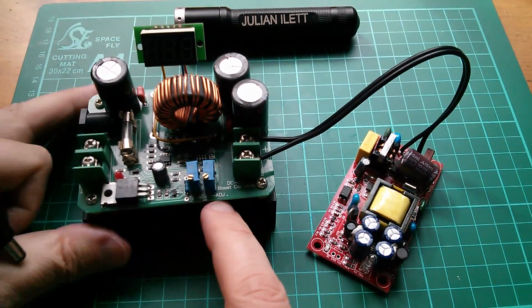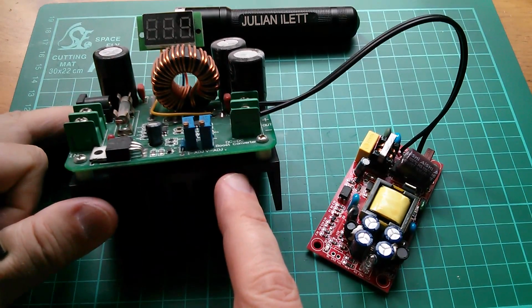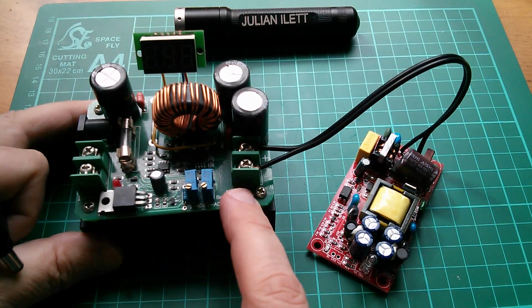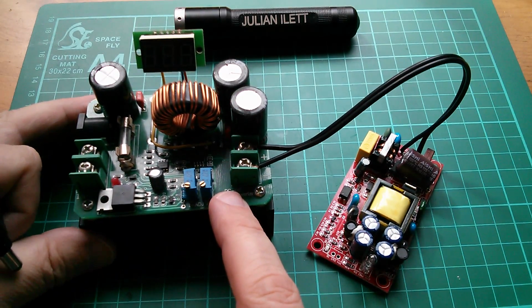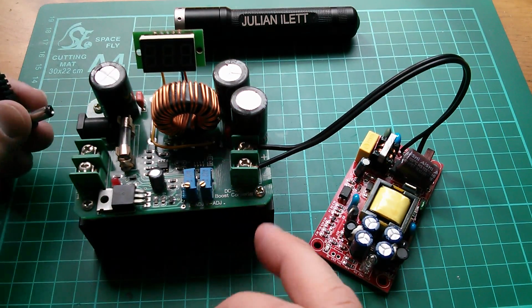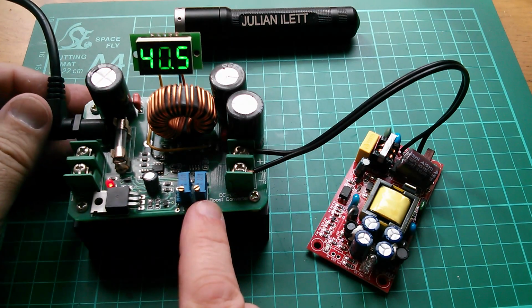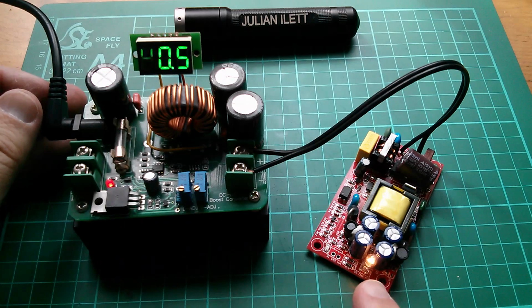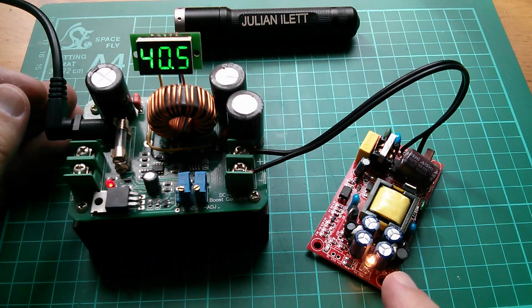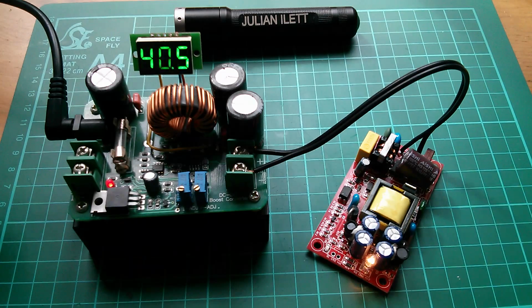So this is the boost converter that I really want to use, because I've got a couple of these things, one of which I can just leave outside permanently in a weatherproof box, of course. So let's plug 12 volts into that, and I've no idea what voltage this is set to. Well, it's only set to 40 volts. That even comes on at 40 volts. It took a while to come on, but that's pretty amazing, isn't it? So this thing works at a voltage well below its official spec.